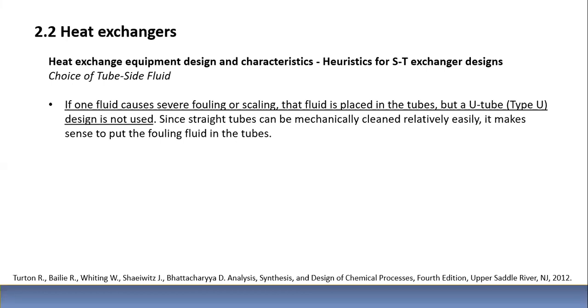If one fluid causes severe fouling or scaling, that fluid is placed in the tubes. But a U-tube, a type U design, is not used. Since straight tubes can be mechanically cleaned relatively easily, it makes sense to put the fouling fluid in the tubes.